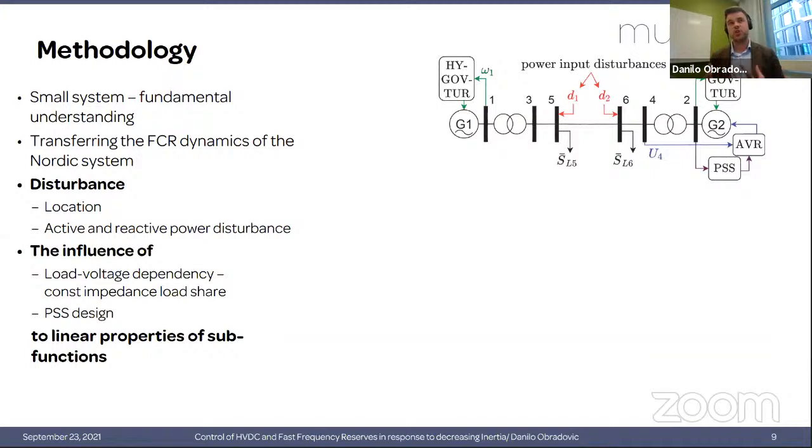And here, when we change the inertia value, for example, we change the generator time constant. Of course, you know that in a real system, that's not realistic. I mean, you have to basically implement power converters and decide if they're going to be PQ or PU controlled, which will affect the load, of course, in your frequency response.